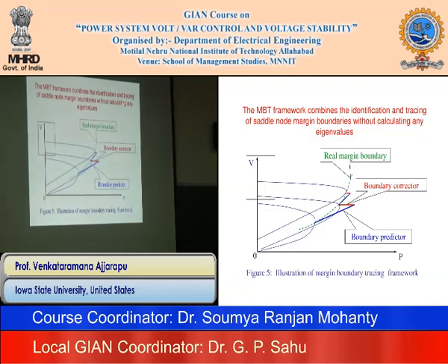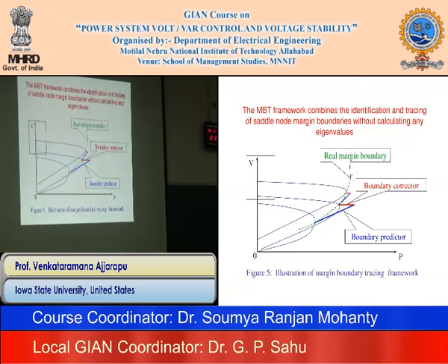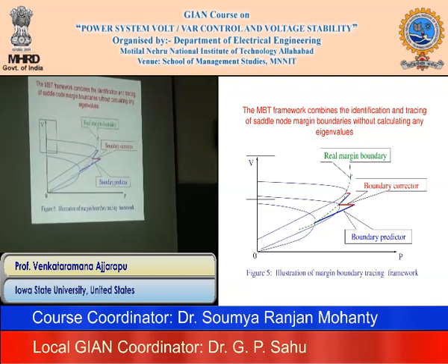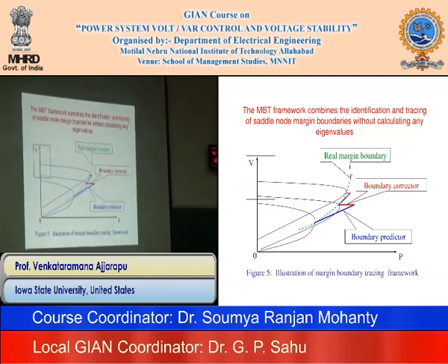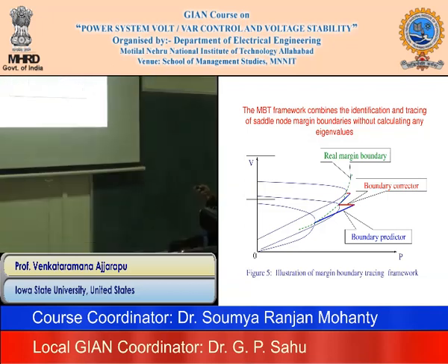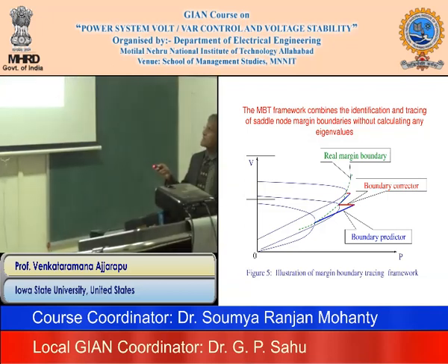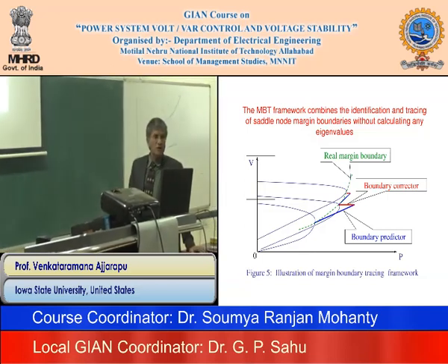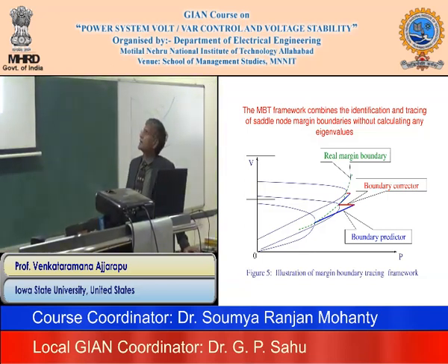And you got to this by some control, right? Remember in the PV curves, you got that one by putting capacitors. So the capacitor is a control, right? With capacitor control, you got this boundary, right? So if I use that capacitor as a continuous variable, B, susceptance is a continuous variable, I can take that one as a parameter and actually extend this to further increase.